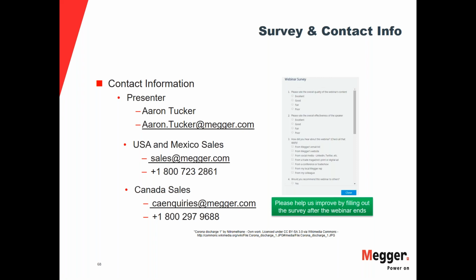But again, it goes back to if you don't know the full characteristics of the transformer, you need that information, because there may be something you don't know about, some kind of internal grounding, where you could either damage the equipment or injure somebody. So unfortunately, it's always best to have that information. If you don't have it, resort to people that have experience with testing these, or find one that's like it, or use the vector find. Again, that comes back down to safety, whether you may in fact do the test incorrectly or test the unit in a step up mode when you didn't mean to.